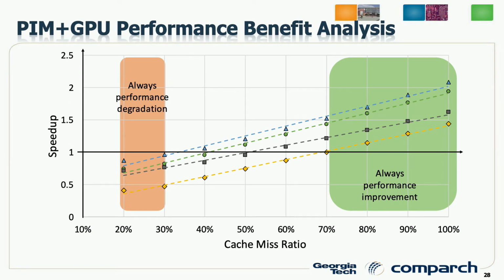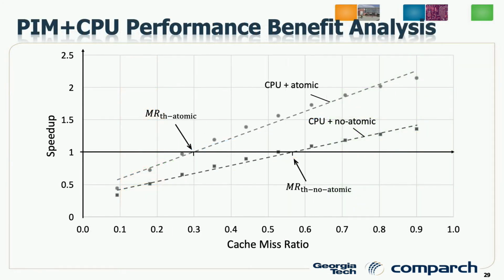This is also showing the ratio based on the cache miss ratios. Another important factor we found in this PIM was the benefit of atomic operations, which comes with the memory conscious models. What it means is, in the CPU or GPU, especially in CPU architectures, when multiple threads are accessing the same data locations, atomic operations are used to protect from multiple threads accessing data simultaneously.